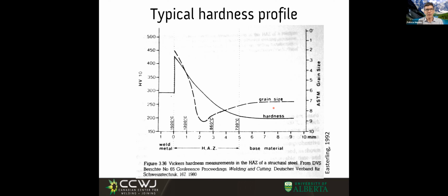Now, more hardenable means it takes longer to transform. And transformation happens by nucleation and growth. Nucleation tends to happen at grain boundaries because they're high energy places. If I have a big grain of austenite, I have much more volume. My volume to surface area is much towards volume, and to transform that volume takes longer because we have fewer nucleation sites for the ferrite.